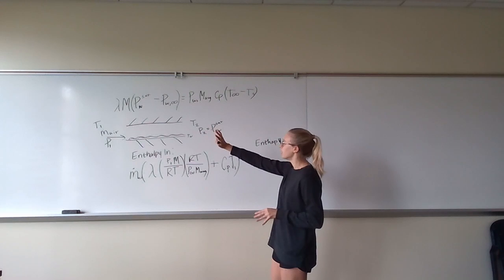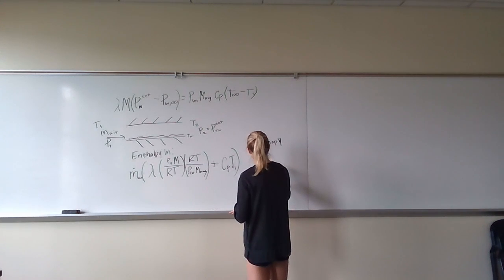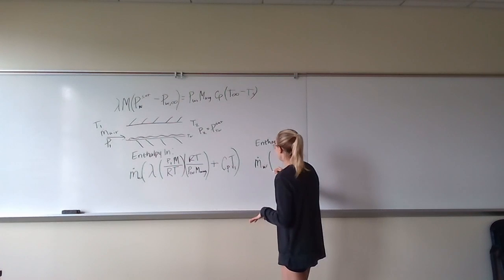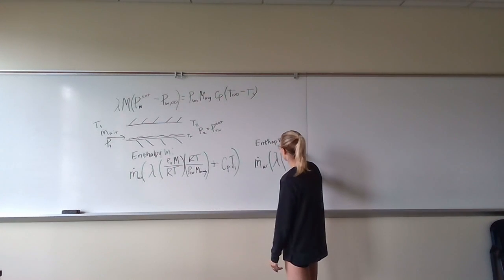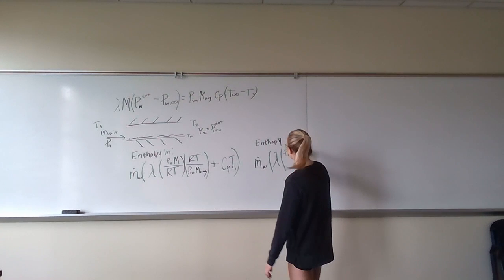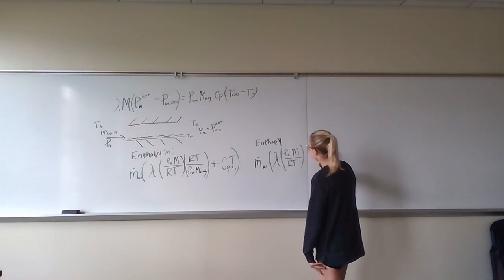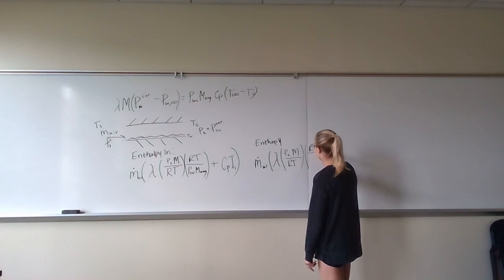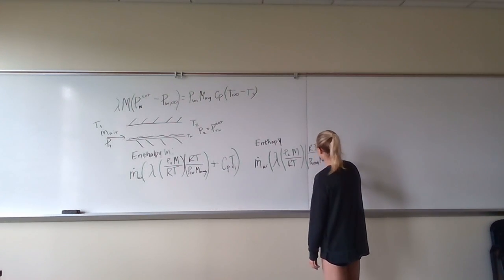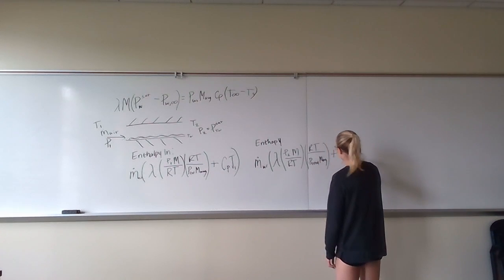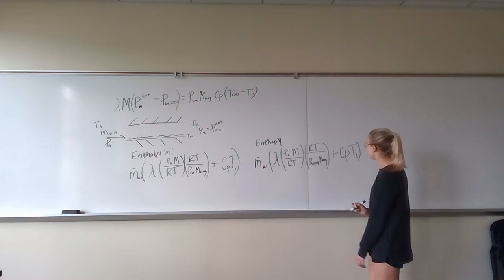Okay, and then for the enthalpy out, it will be very similar, but just using the terms for the air going out and the partial pressure of the water going out. So we have, again, the mass flow rate of the air, since this will remain the same, and then the heat of vaporization, and then instead of the pressure of the water going in, we'll have the partial pressure of the water going out times the molecular weight divided by the ideal gas constant times the temperature, and then again the same, the ideal gas constant times the temperature divided by the total pressure times the average molecular weight, and we want to add the heat capacity times the temperature of the air coming out in this situation.